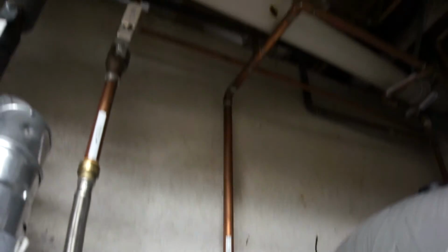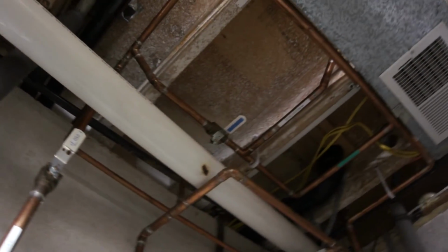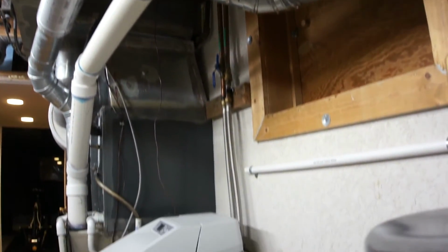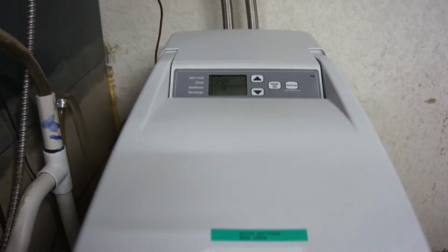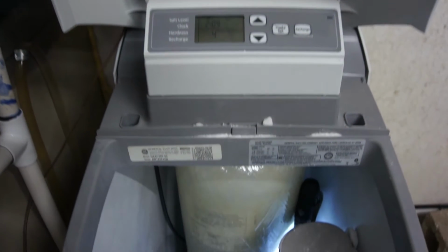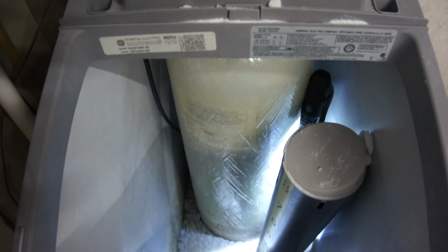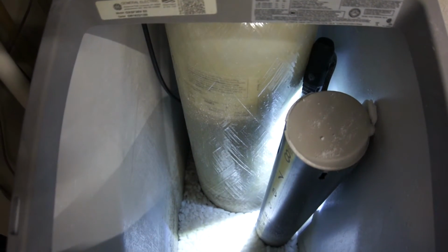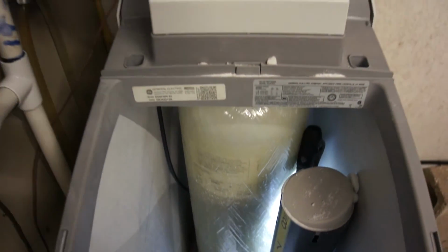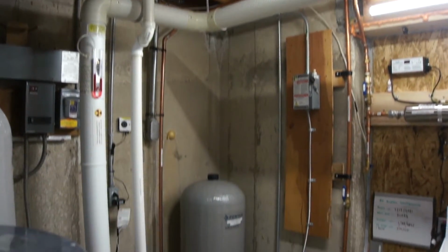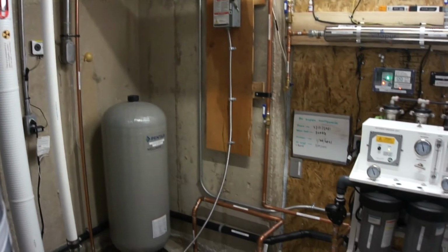The raw water then flows through a series of pipes from the pressure tank to a water softener. Most, if not all, reverse osmosis manufacturers say that their system won't work above 2,000 parts per million on TDS. Since ours is so close to that, the water softener reduces the hardness a bit. This reduces the potential for fouling the RO membranes and improves efficiency of the system. The softened water is then piped along the same route to the inlet of the reverse osmosis unit.